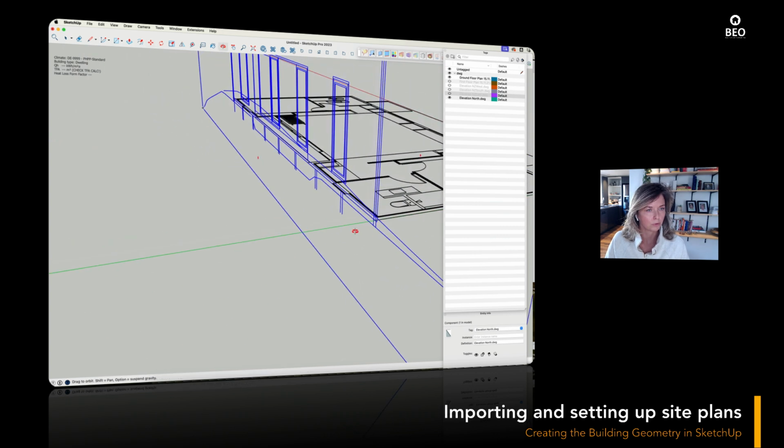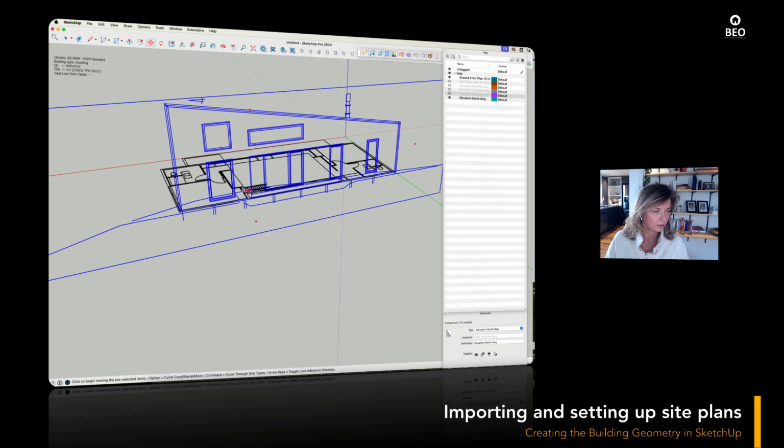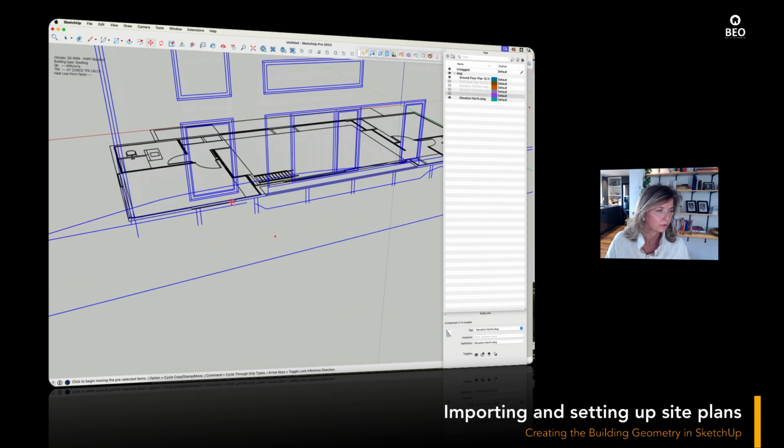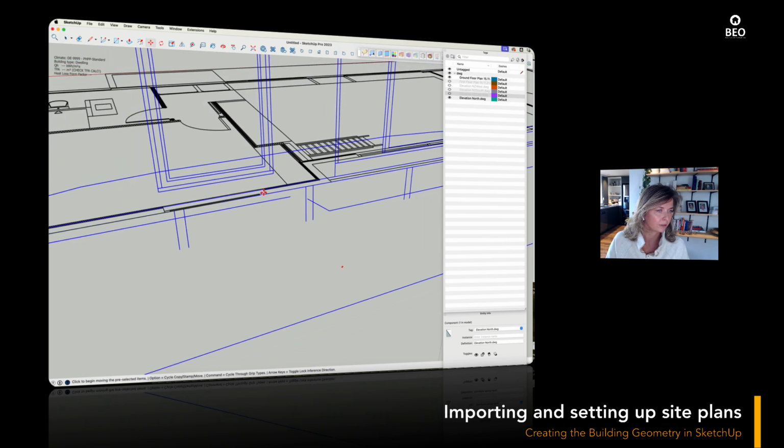So in principle these should align. I know they don't always do that, but you can use window detailing as a reference. For example, now we've got this aligned on the outer line here, but we could check if this window aligns with this here by clicking again with the move tool onto our reference corner here.